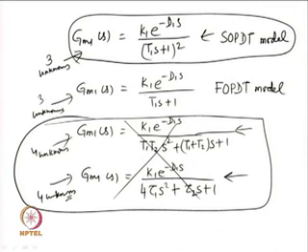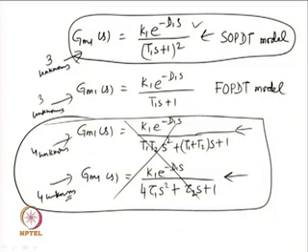Coming to the first two, the first order plus dead time model has got 3 unknowns, whereas the second order plus dead time model of this form has also got 3 unknowns. So, why not use the higher order transfer function model that can replicate the dynamics of many practical systems. That is the benefit we get from this second order plus dead time model, and that is why I am going to use this transfer function model in our analysis.